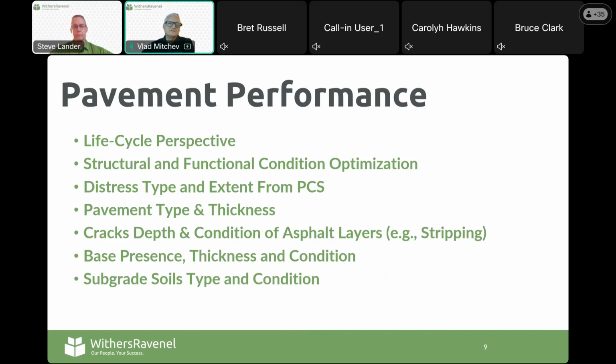That can help us engineers and municipal engineers decide: can we mill that deep, and is there anything to hold the pavement we are thinking of putting on top? So in some cases, stripping in lower layers of the asphalt structure will not allow some of this mill and fill resurfacing.